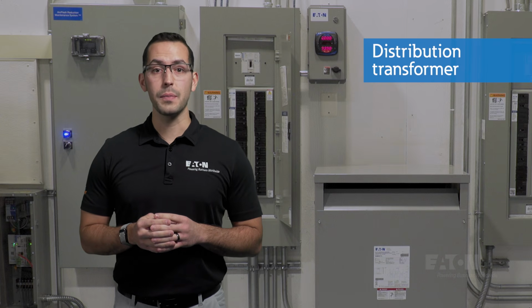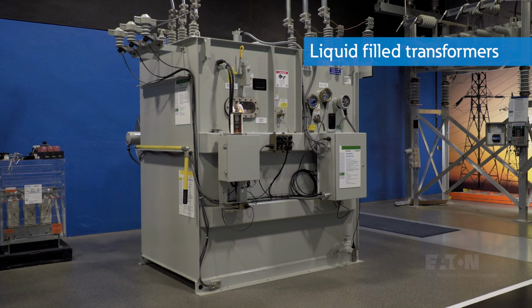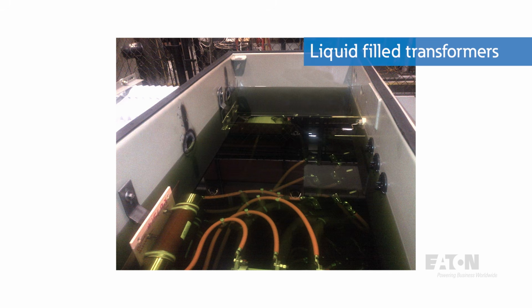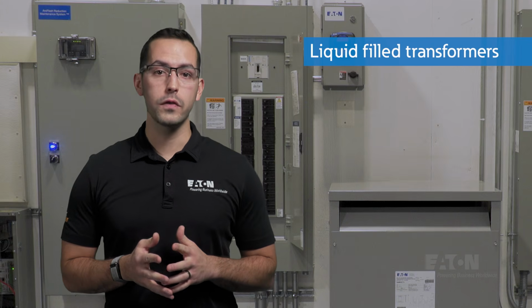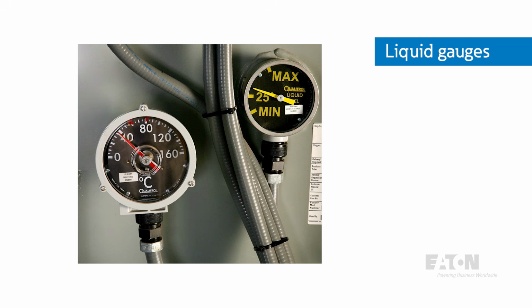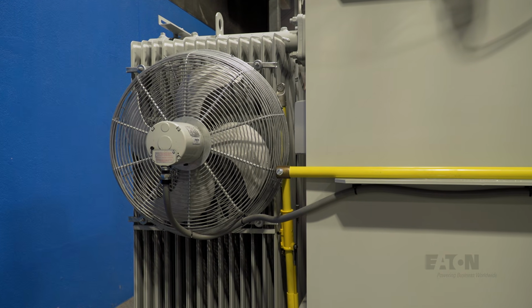These transformers typically fall into two categories, liquid-filled or dry-type. Liquid-filled transformers have coils that are immersed in insulating fluids such as mineral oil or natural ester fluids. These fluids provide good electrical insulation and carry heat away from the core and windings by convection. Fans can be added to dissipate more heat and achieve a higher power rating.